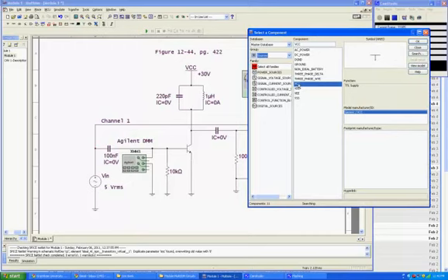We have VCC, which is just a typical DC power supply. By default, I think it's 5 volts in Multisim, but you can certainly change it. We also have a ground. This is earth ground, and this is what we'll use primarily for our circuits in this course. You also have a digital ground, but we won't investigate that. Lastly, we have our AC power source.